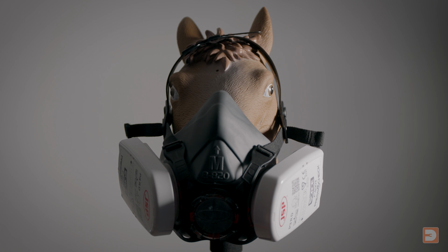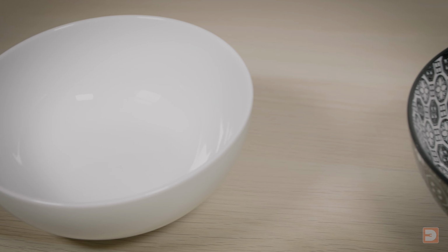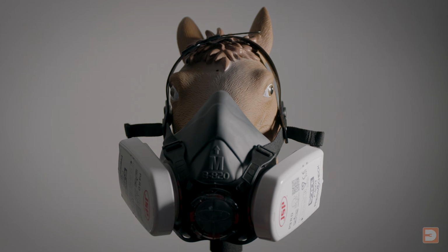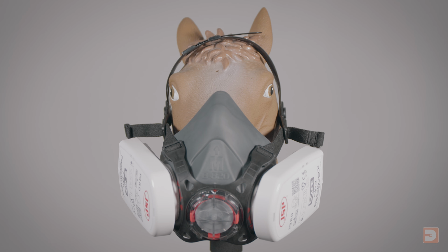Unlike other 3D scanners, which rely on special sensors to determine distance and shape, photogrammetry uses this software to simply compare the colour information of standard photos. As the software establishes key points in different photos that match, it can then determine how the photos need to be folded so that all the points fit together in 3D space. It's due to it being entirely reliant on colour information from photos that unique and visible texture or pattern on the object, as well as consistent lighting, is extra important in photogrammetry.